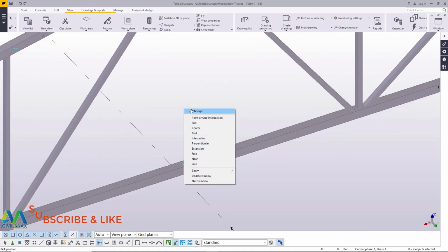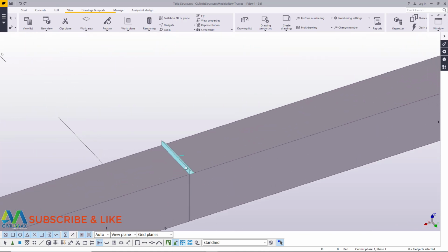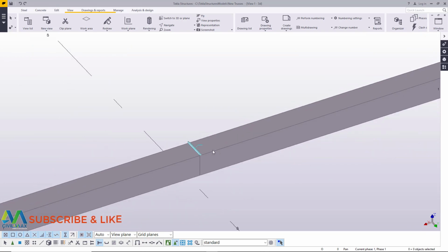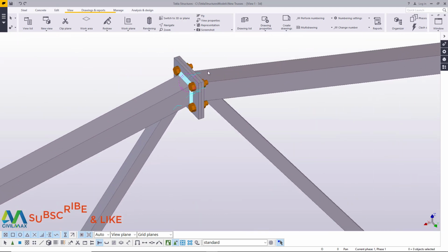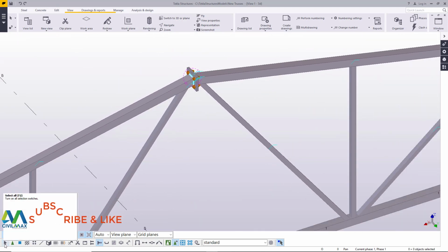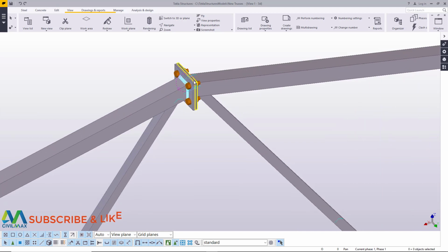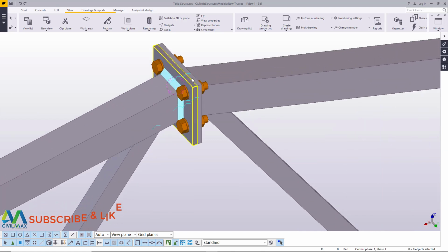Now what do? You can see down here a symbol of weld, and we want to remove this. Another thing, if you can see now I'm trying to select on this, and you cannot see anything getting selected because we've disabled any kind of selection here while we are doing the bolting offsets. Now I'll enable everything here by clicking select all. You can see when I mouse over this button here, you can see turn all selection switches on. I'll switch on that, and everything will be back to selection. Now I'll come here and select it.